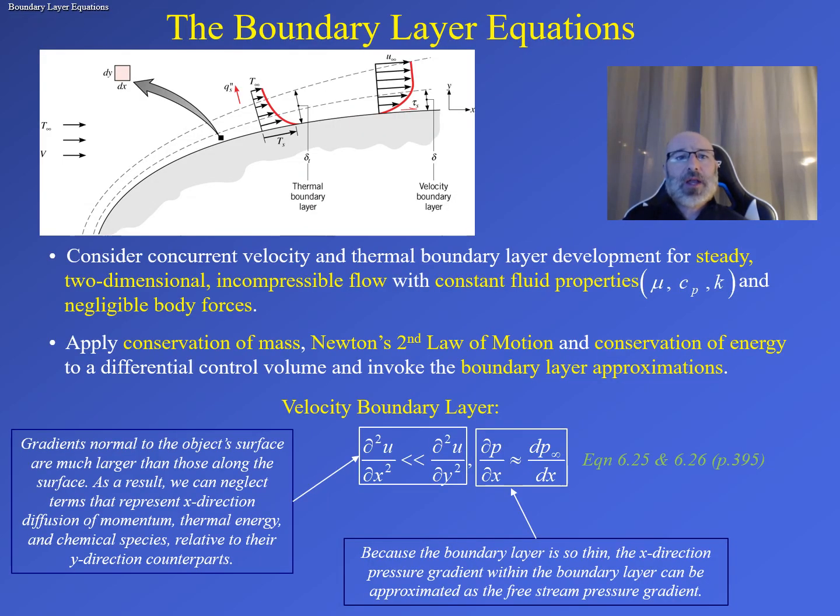So moving on, I want to now take a look at our boundary layer equations. We can improve our understanding of the physical effects that determine the boundary layer behavior, and further illustrate its relevance to convection transport, by considering the equations that govern the boundary layer conditions. These are illustrated in this figure on the left. Within this figure, we have our delta T, our thermal boundary layer, and we also have our velocity boundary layer thickness, our delta.